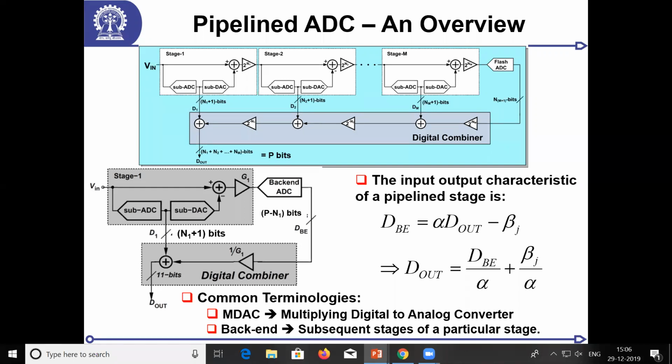This is one of the challenges, because in nanometer CMOS, this part of the circuit is messed up. It's not great. So I have to fix this circuit, but I don't have access to it. As soon as I put access to it, the performance speed of the circuit drops, because if I'm bringing it to the pad, performance drops. So I cannot bring it outside either. I have to figure out the performance by looking at only the inputs and outputs. I have access to nothing else. And that is what happens in a scan chain also in the digital domain. I don't know if you know what a scan chain is. No, okay.